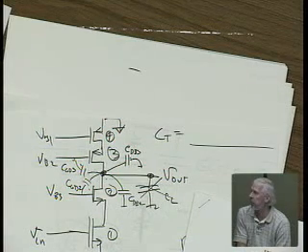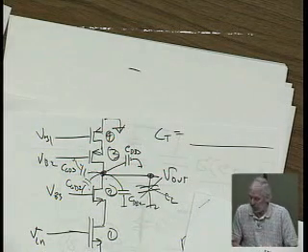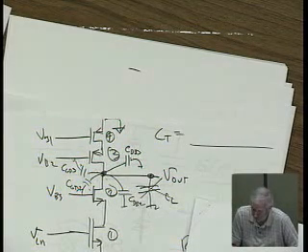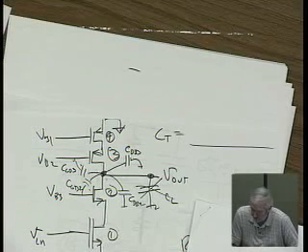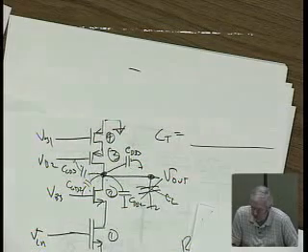You can't look at this one by itself, because it's the relative position of the pole locations and the time constants. At the moment we have a very big value for R out times C here, and for this point we have a very small value. So what should we do for this point? Is anything going to change because of this other system? No, I think it's right.